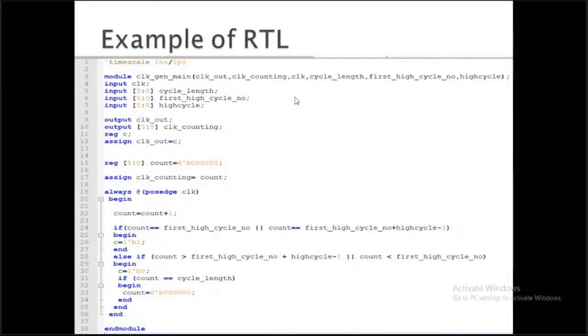But in real testing, we make different kinds of clocks. So here I have defined a very basic clock generator, where we define a complete clock cycle and generate a clock with different kinds of duty cycle. In a clock we can say we have two parts. One is how it will work. Some circuits work on the positive edge, some on the negative edge of the clock, and latches usually work on the high level and low level of the clock.